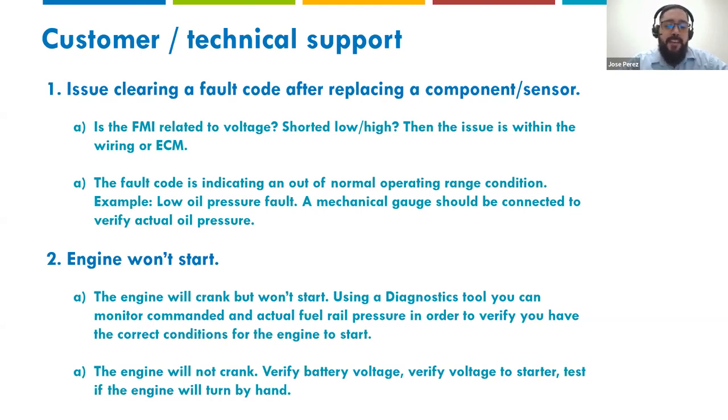That's very important. And then obviously, if the engine will not crank and will not start, we would probably guide you in verifying the battery voltage and the voltage to the starter. And then obviously the engine has to be able to turn by hand. If it cannot turn by hand, it is seized, and you won't be able to start the engine.